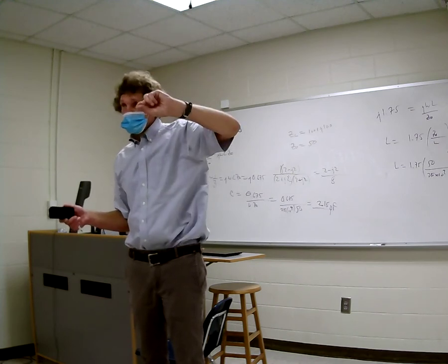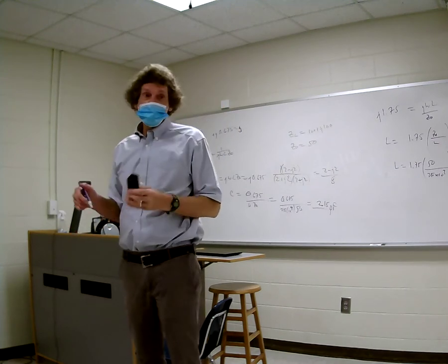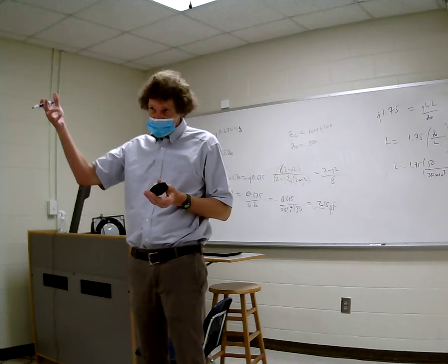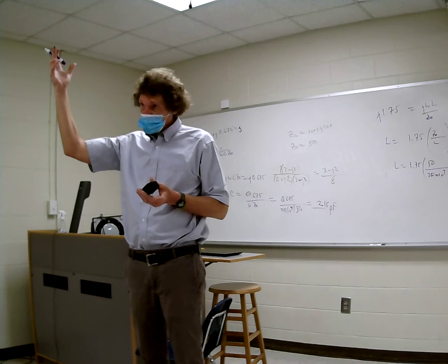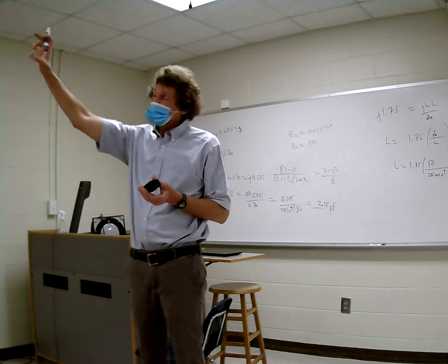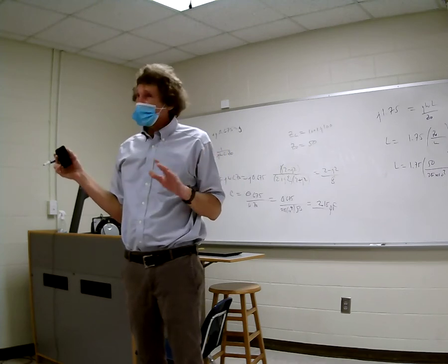Do you remember this? Once you did that, you got an offset current, and then you could say the amplification factor was basically gm, right? And gm is the current I divided by 0.025. You don't remember doing this? And then it's going to be that times the resistance of the load, and that would give you your voltage gain. But I'm not going to go through that with you.